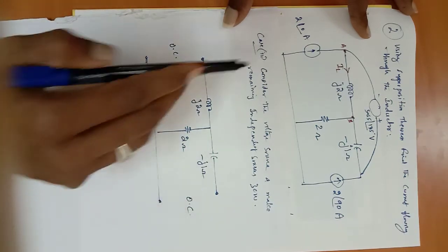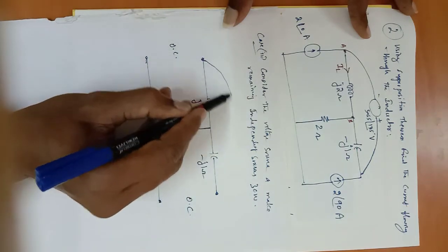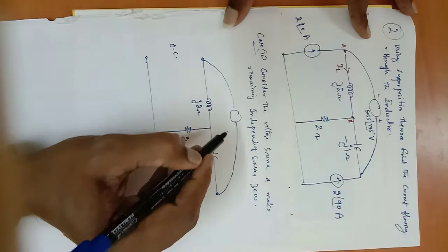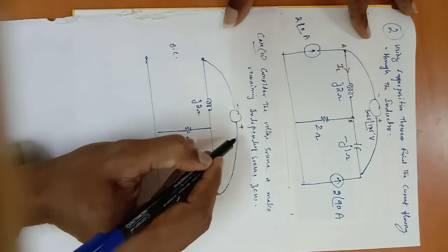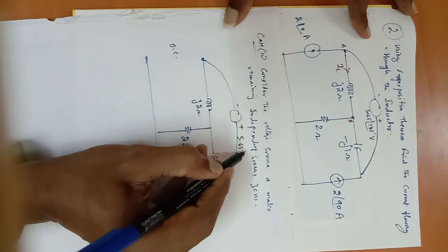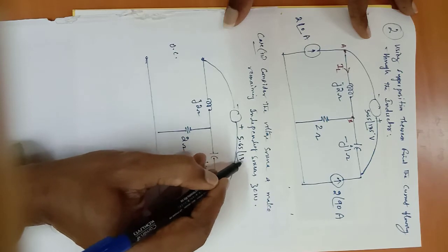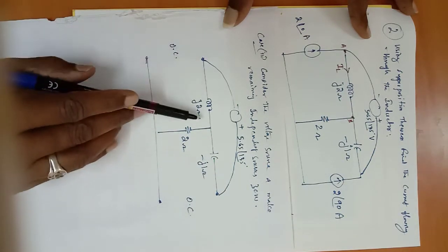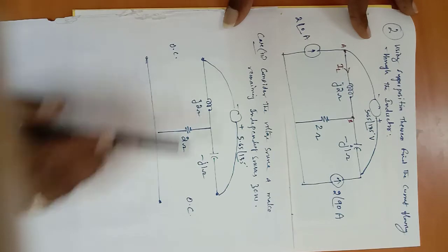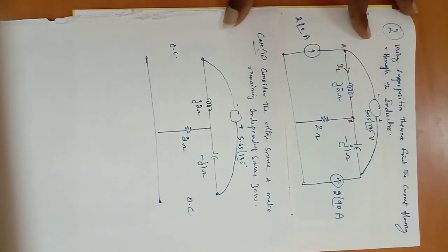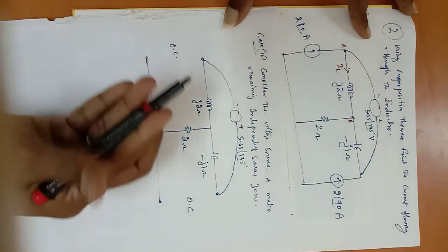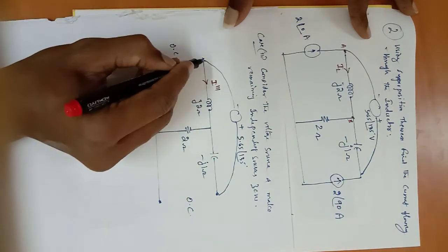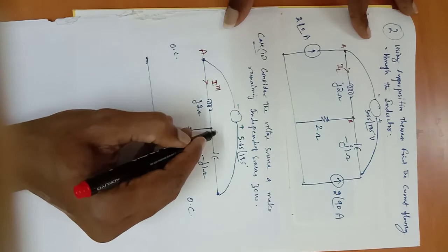I am considering this voltage source. Now rewrite this voltage source. Polarity is important, plus or minus. This is 5.65 at an angle 135 degree. Now what is your intention? Current flowing through inductor I need to find. Let us mark that current as I triple dash. So mark here as I triple dash flowing from A to B.